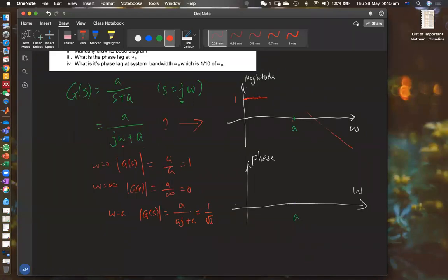Somewhere over at this point, you got 0.707, equal to 1 over square root of 2. All right, so if you draw the whole thing, link this together, it looks something like that. So there's a corner cut off. So that's your Bode diagram in the gain frame. This is your gain. And at this corner, you get this drop a little bit. So it's not perfectly like two straight lines.